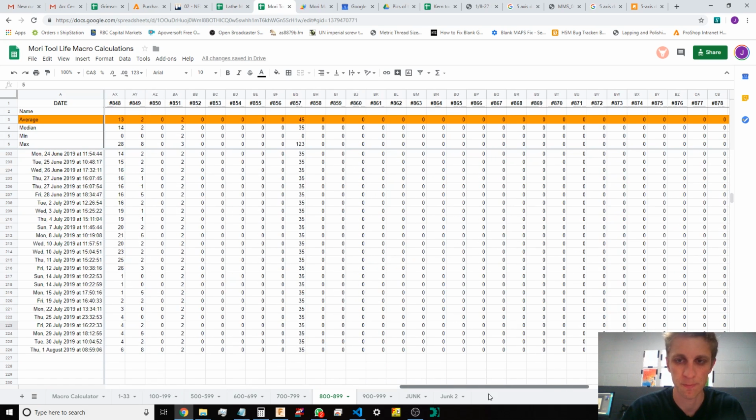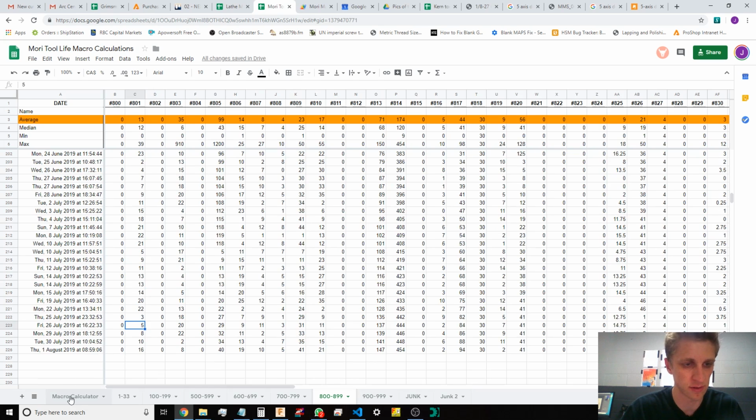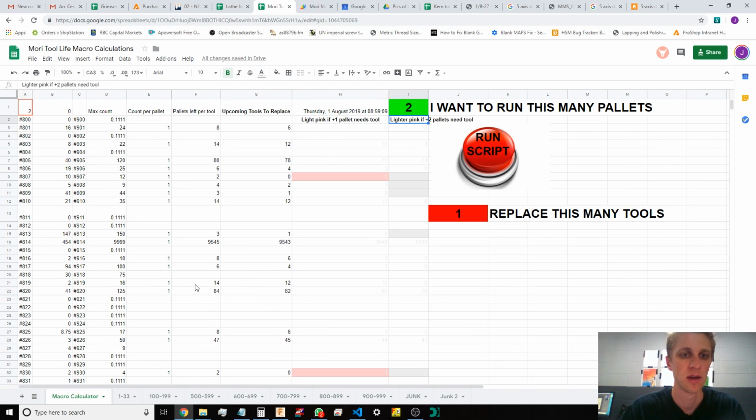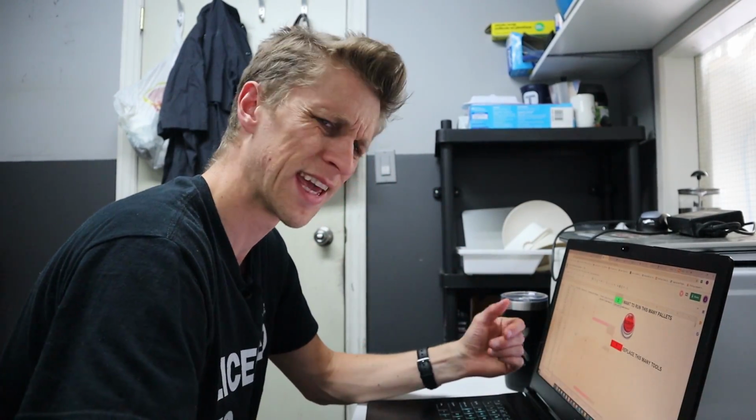So, yeah, I don't often use these. I use this one every single day, and it worked great. The trick is, I don't want to use the USB stick anymore. I want that data to automatically DPRNT every single time from the machine, say at the end of every cycle. When it hits M30, it automatically DPRNTs, and then just goes to my Google Drive, done, automatically synced. That's my goal. I can't figure it out yet.